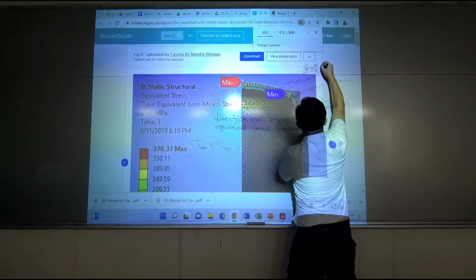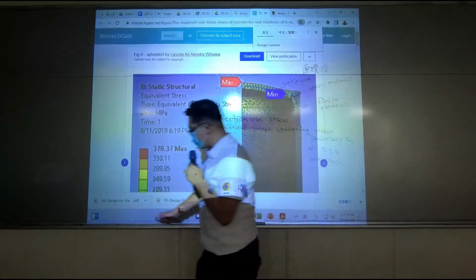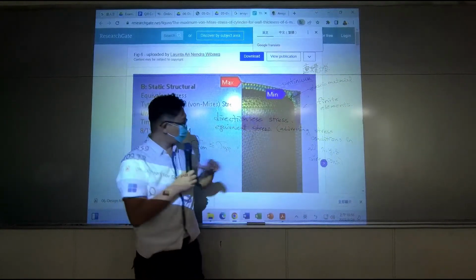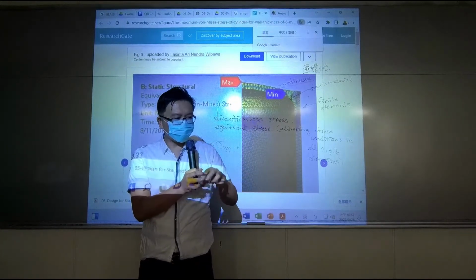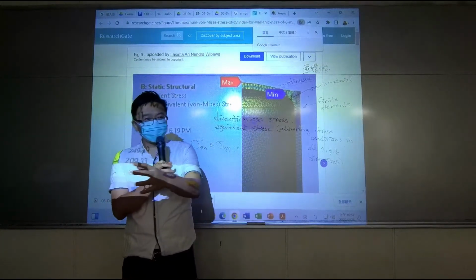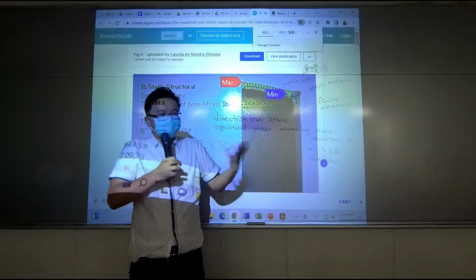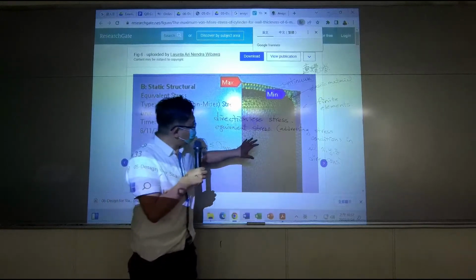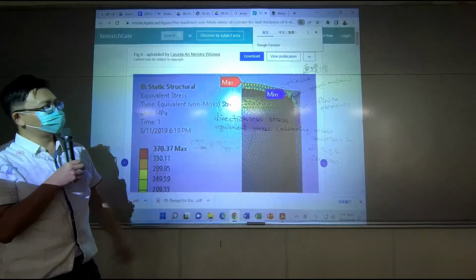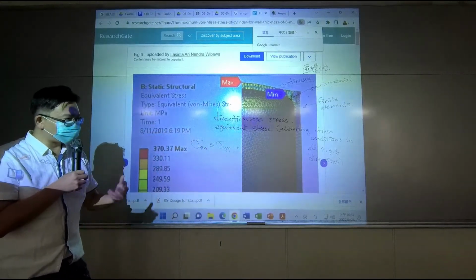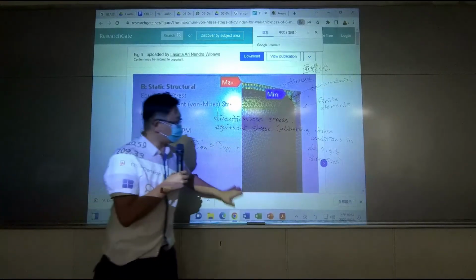It's a mechanics that describes continuous deformation. If one material deformed this way and the item next to it deformed in the other way, they don't have continuous deformation, then it breaks, right? So for finite element, we assume continuous flow conditions, continuous deformations. So that's how the software can model the whole thing.